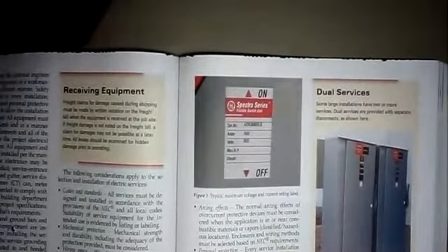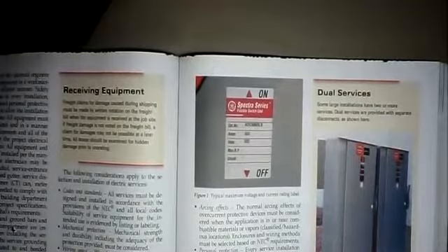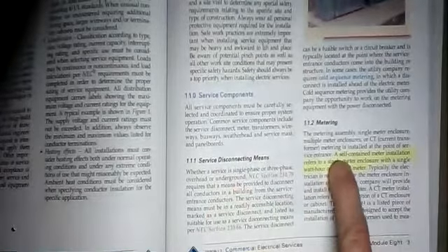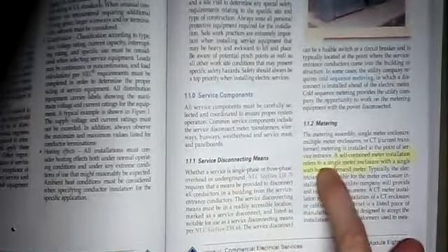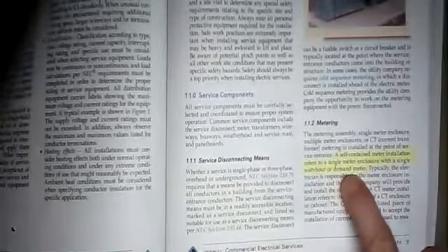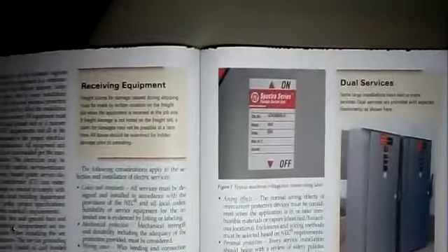and it's been delivered to the job. And over on page 3, the right-hand column, very bottom of the page, they're talking about metering. It says a self-contained meter installation refers to a single meter enclosure with a single watt-hour or demand meter. Most of the times, the meter will not have the full current flowing through it like at your house.